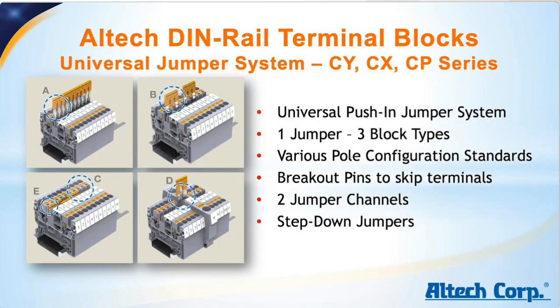Now, compared to the CT series, all the other series which we carry cover all connection technologies like screw, spring, and push-in technology. That's our CY, CX, and CP series. And they all utilize the same universal push-in jumper system. So regardless of the series, it's always the same jumper, which makes it much more convenient to keep inventory, because you have a lot fewer part numbers than if you would have a different jumper for each series.